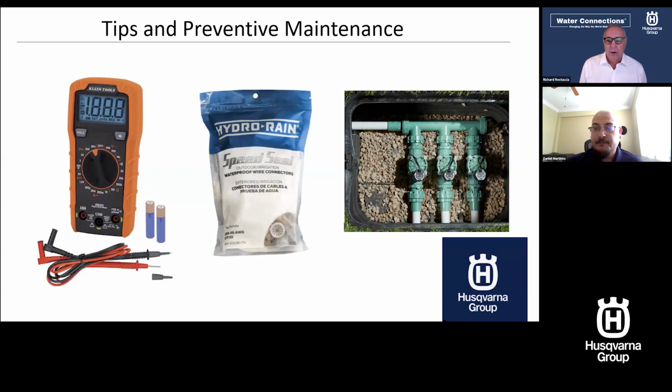Yeah. So those valves look kind of cool with the nuts on them. You can just spin those in and out. Absolutely. So shut your water off. Are you talking about the unions on the side to replace? Yeah, absolutely. Those are nice Orbit valves with the union on there. No need to cut or re-glue pipe. You just spin those union nuts off and swap it out with the new valve.